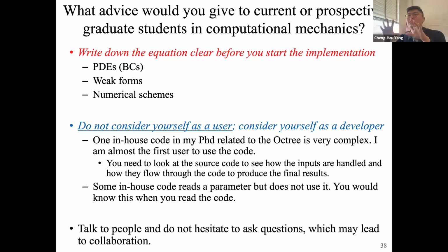We should write down everything very clearly, derive the weak form, use the numerical scheme to do the discretization, and write down what the matrix should be after we do this. And when we do the implementation, we just need to follow the matrix correctly.